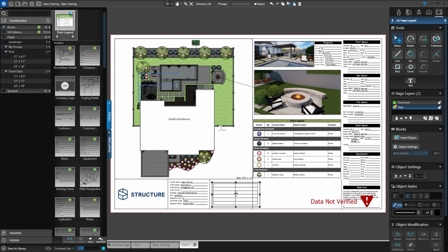To resize the column, hover your mouse over the line of the table on the right. When your cursor shows a line with 2 arrows, hold down the left mouse button. As you move your mouse, a purple dashed line appears marking the new size. When you have the width you need, release the left mouse button and the table will resize. Use this same technique to move the center line.